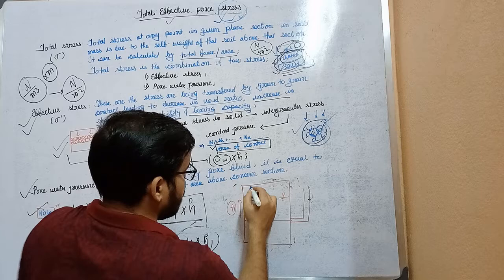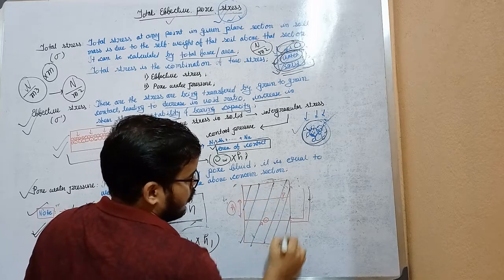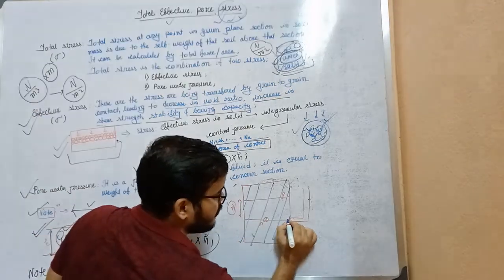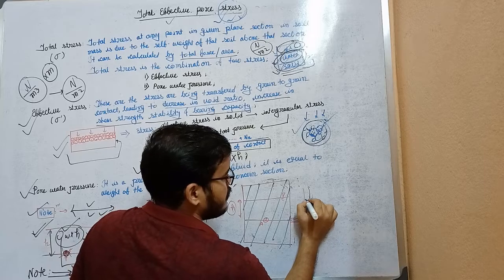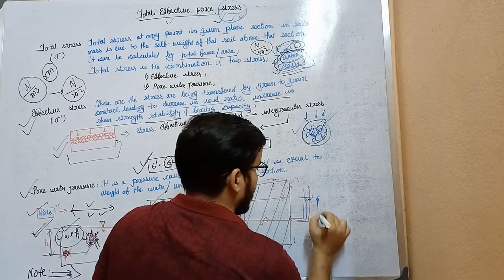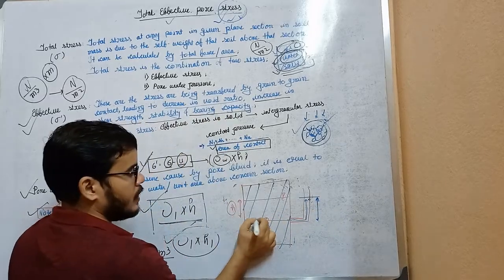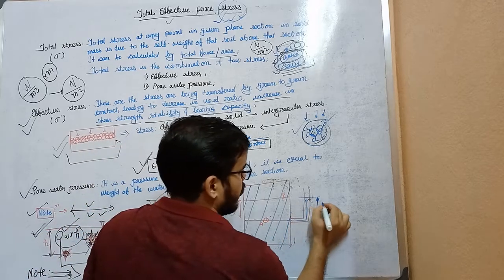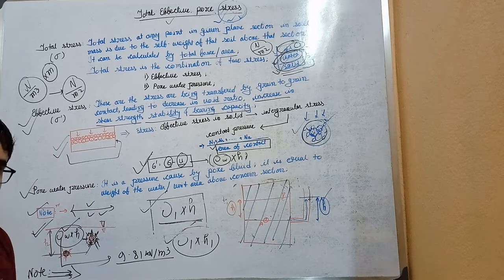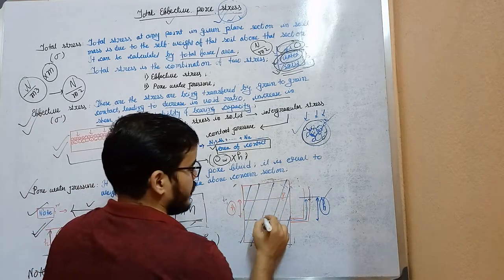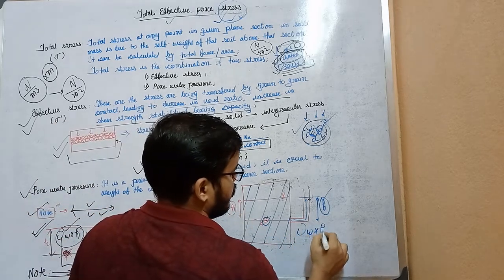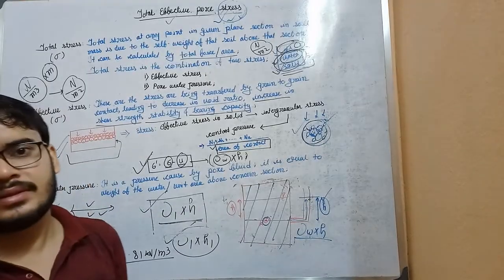The water below this soil is under pressure, and when it gets some free space, it will rise in this tube. The amount of rise will be the amount of pressure inside the water in this soil. Okay, so after getting this height, you can understand the amount of pressure generated by the water inside this soil. Then you can multiply this height by the unit weight to get the pore water pressure. Okay.